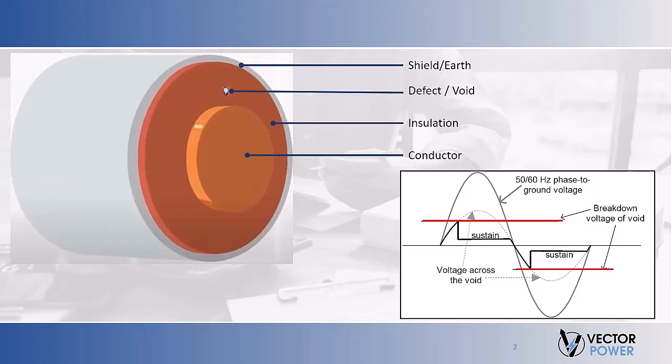Partial discharges are tiny electric sparks that can occur at defects in insulation, along interfaces, or surfaces between a conductor and a floating conductive component, not connected to the high voltage conductor or the ground, or between floating conductive components. When the intensity of the electric field is strong enough to ionize the medium surrounding these components, partial discharges will happen. These discharges do not completely bridge the insulation between the conductors.